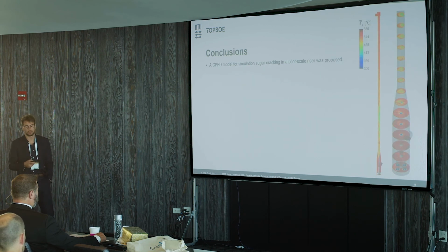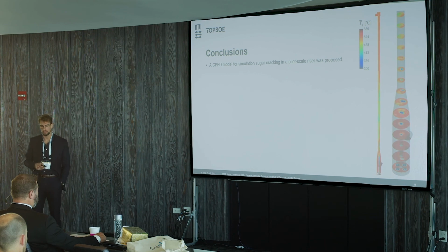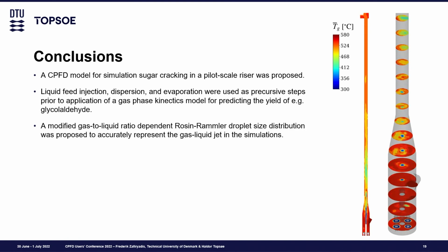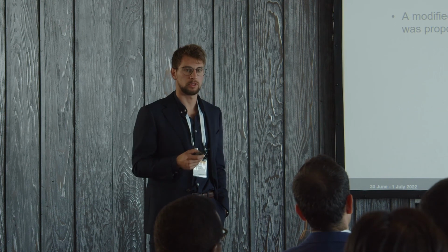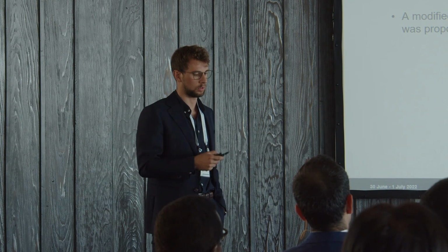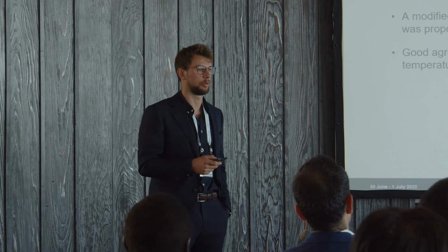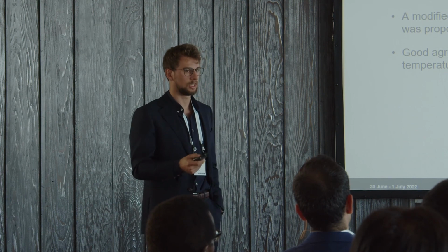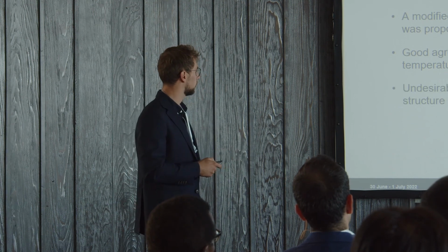But it's a bit sad because we have a quite nice setup for all the thermal parts, all the hydrodynamics part of it. We have this liquid injection, dispersion, evaporation model that seems to work quite well. We have been using a lot of time on the boundary conditions to get that right for the feed conditioning zone. And we have seen quite good agreement both on hot conditions and cold flow conditions in terms of overall pressure. Thermal parts are still lacking a bit, so we're doing whatever we can to improve that.